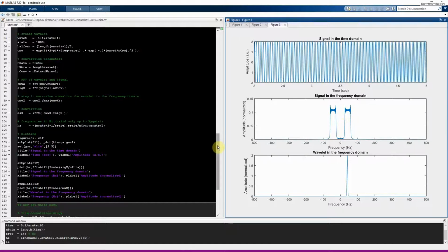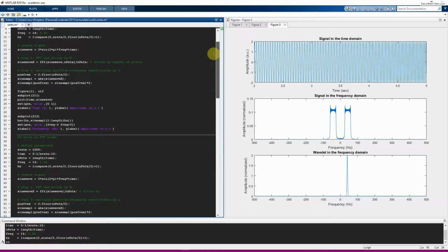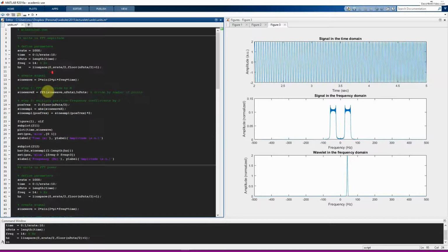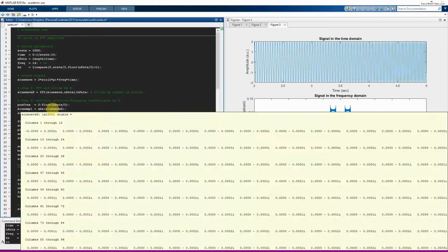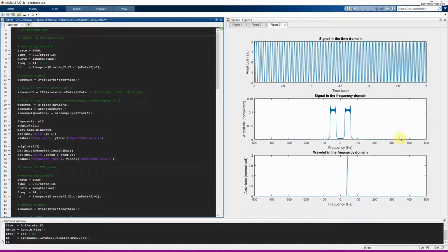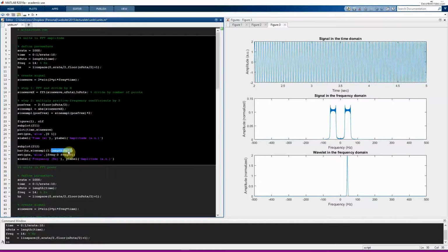Now, when we extracted amplitude from the FFT here, notice we didn't flip the negative frequencies and sum them back on the positive frequencies. We actually ignored all of the negative frequencies. That's here, so we just take one up to the length of Hertz, which is going up to the Nyquist frequency. So what we did here was actually only take this side of the Fourier spectrum.